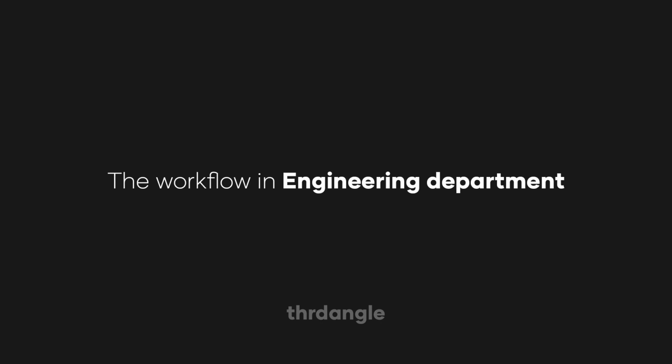The next thing is making an estimation nesting for the material estimation. Making a DXF file or drawing file for our machine interface, for our laser machine, plasma machine, all the CNC machines. Then making a drawing for all the critical parts. That means if we are changing a feature on the part, then we need to generate our own drawing, which is slightly different from the customer's drawing. The next thing is detailing of each individual part.